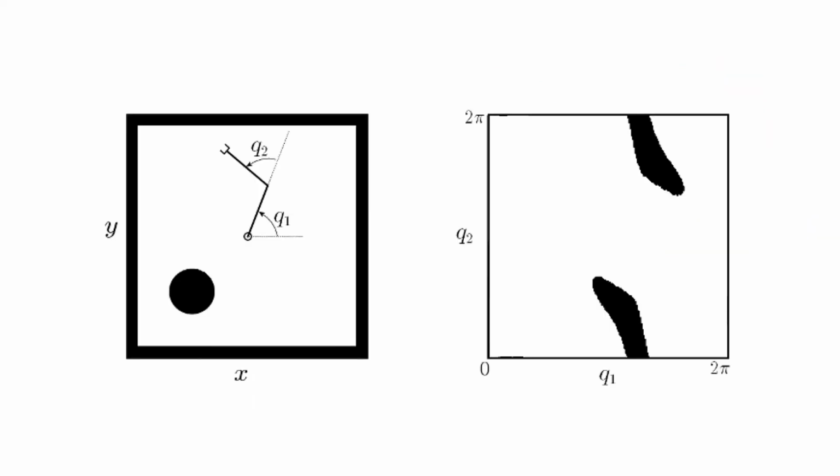And then there is another problem. That problem is that generally the task is defined in the workspace. So that workspace is being shown over here. And you can identify that because this is the X coordinate over here, and this is the Y coordinate over here. And the robot is parked right in the middle of it. Now, generally what happens is that when you have to perform, let's say, a pick and place exercise, you define your exercise in the workspace.